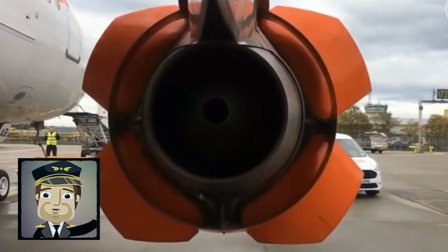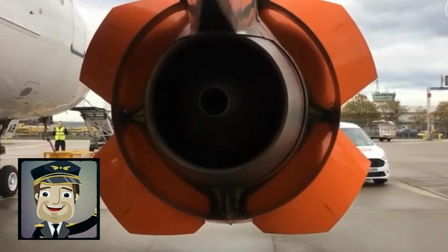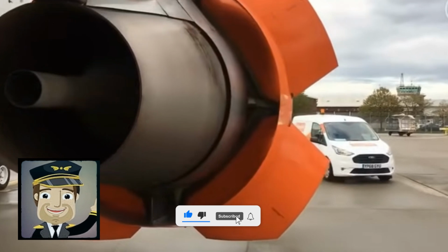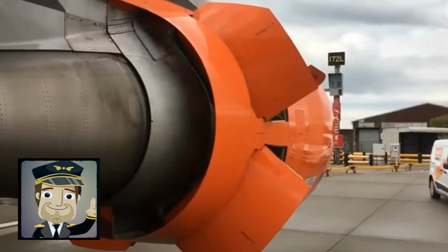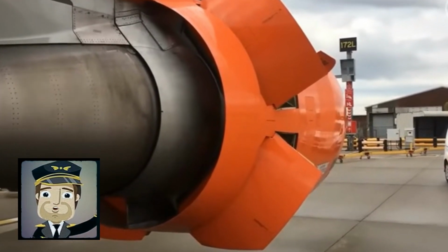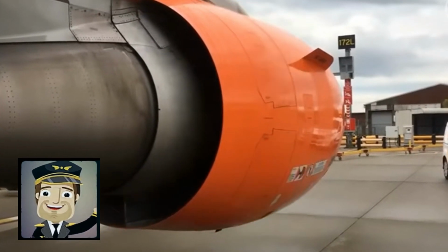This redirection of thrust helps slow the aircraft, but the system is relatively heavy and less efficient compared to modern alternatives. Cascade-type reversers, widely used in turbofan engines, function differently. Reverse thrust is achieved by redirecting the fan airflow, the largest volume of air moved by the engine, forward through special grills known as cascades.